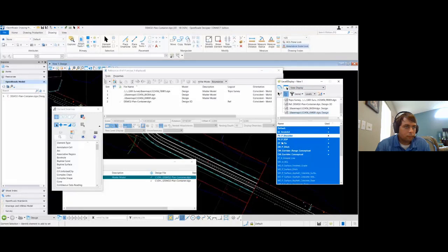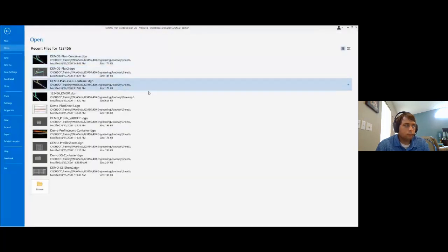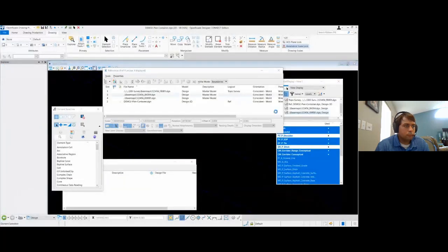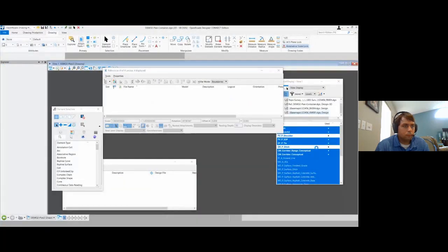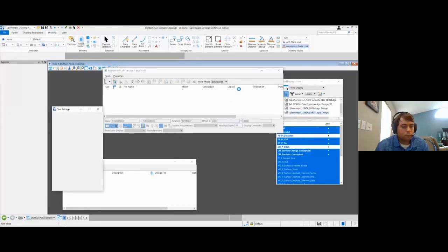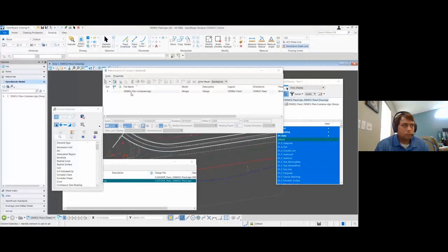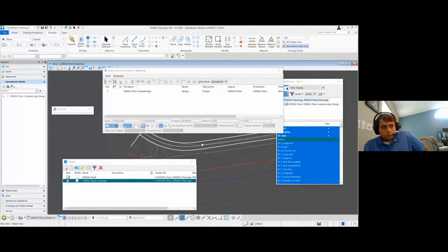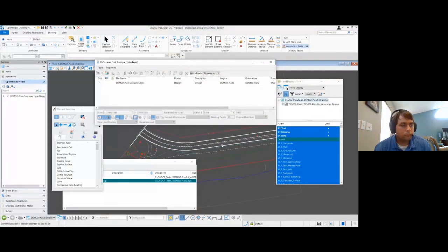So if I turn it off, save settings, and I jump back over to my sheet file, you'll see that it will be off, because that display overrides equal never is saying, basically keep in check with that reference file. So now I see that it is off.